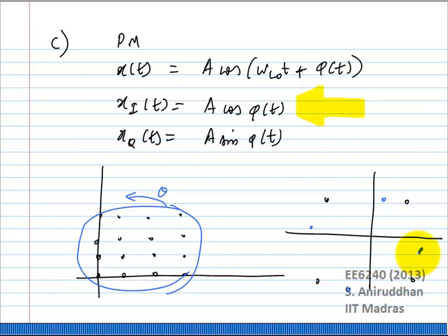The received phase is fixed, the transmit phase is not. For the duration of the frame, the transmit phase can be assumed to be constant. Obviously, for every frame, you will need a pilot symbol from which you will detect this.